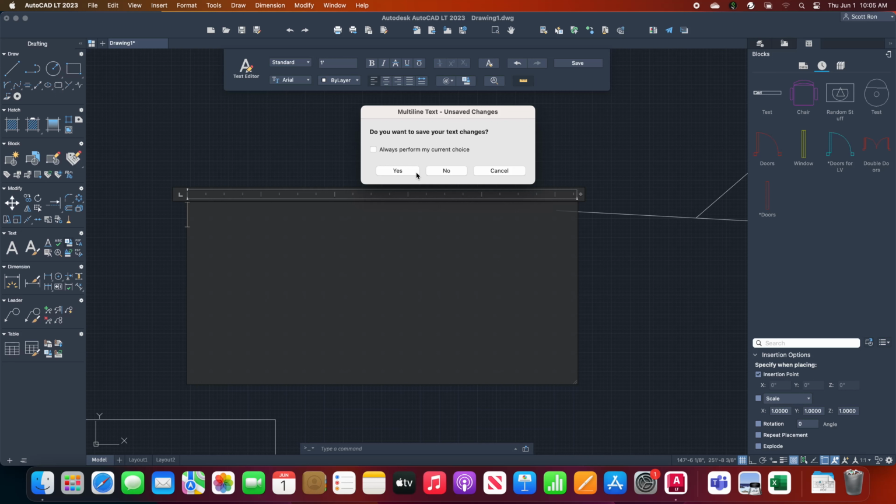Like I think Ron's desire was to have a CAD plan that has all the campus floor plans in one, where you can go to each floor. Imagine having all these texts in one and no separation. That's going to create a nightmare. So it's best to have everything in its own layer. That way it makes everything easy. What you don't want, you can just hide. And if you want to edit something, you can just edit in that layer, so that it does not show up in everything and you're like, oh, now what do I do?